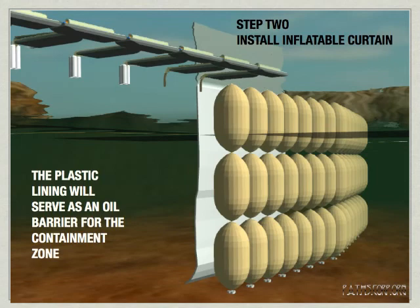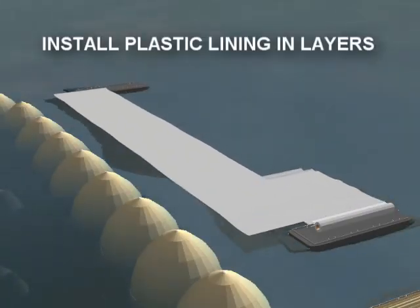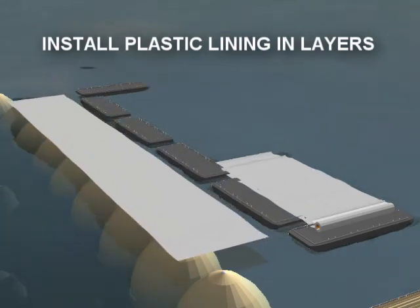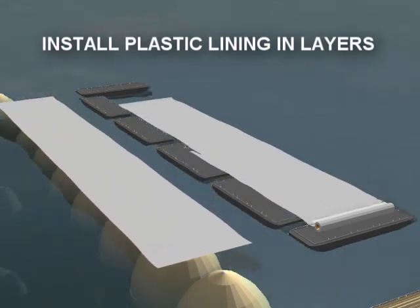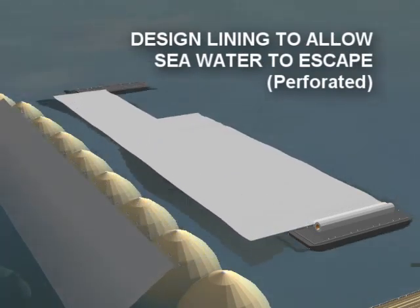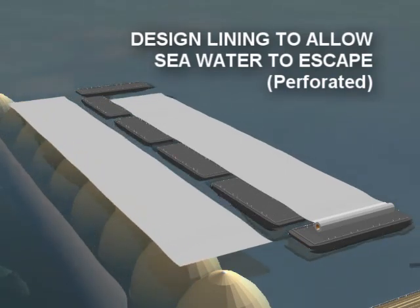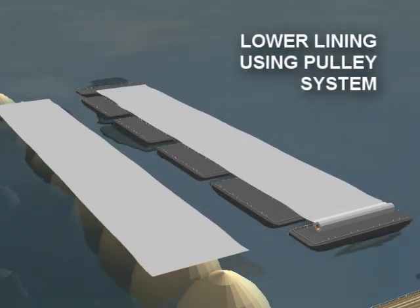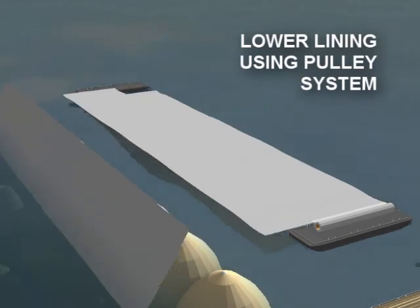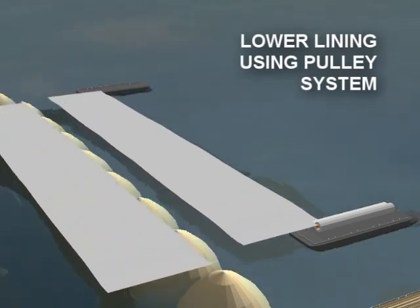The lining will serve as an oil barrier for the underwater curtain. Install plastic lining in layers. Design the lining to allow seawater to escape, or perforate it. Lower the plastic lining using the pulley system.